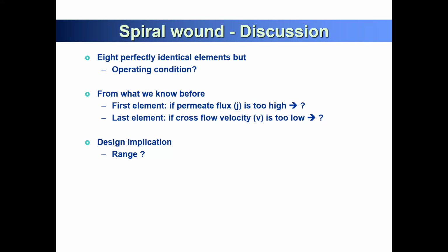If you try your software, you will see you have very strong inorganic fouling, because solubility is too high for calcium carbonate and calcium sulfate. So they are the major initial inorganic scaling, along with magnesium carbonate and magnesium sulfate. These are the main inorganic scaling at the end of the stage, so we just look carefully at concentration and recovery impact.